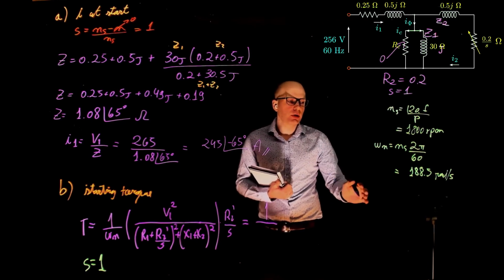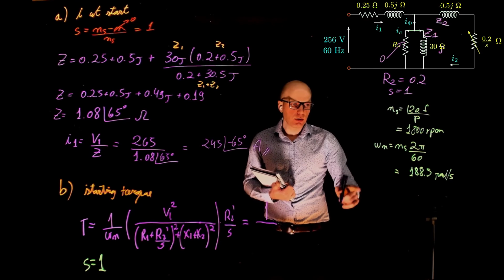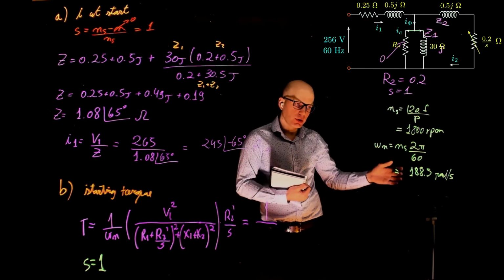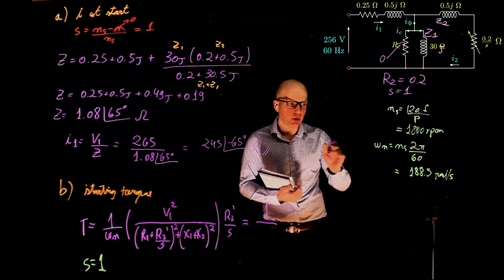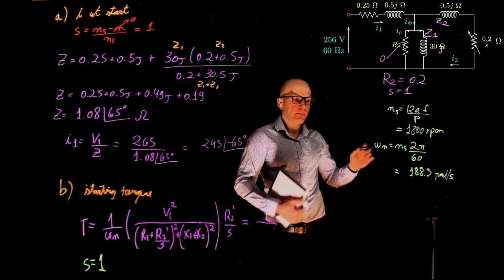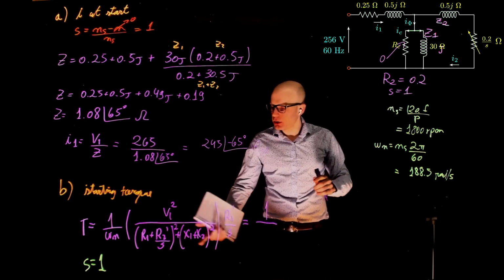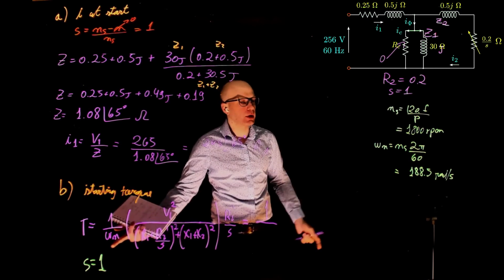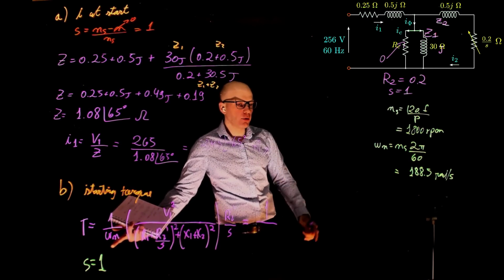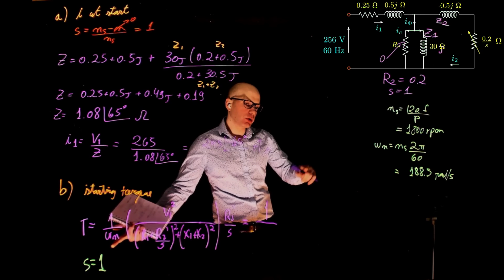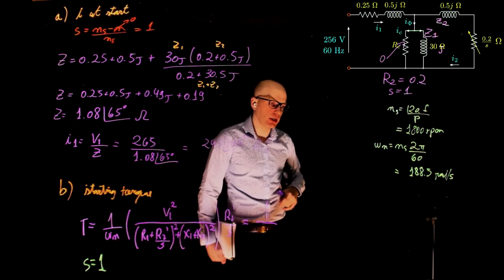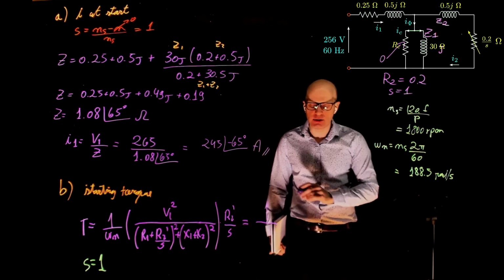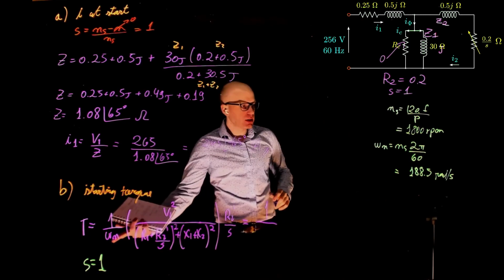That would be the rotor speed with respect to the synchronous speed. That's where the 1 minus s comes in. But here we are dealing with the synchronous speed already, so that doesn't apply. If you had to convert from the synchronous to the actual motor speed, you would multiply that by 1 minus s. But that's a different context. So this is that speed.